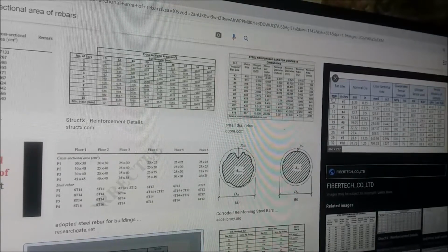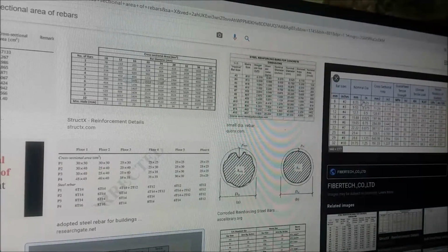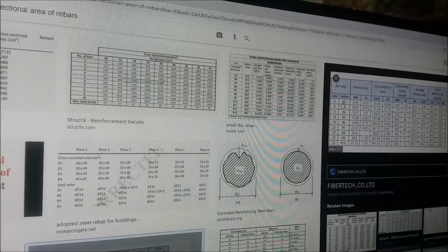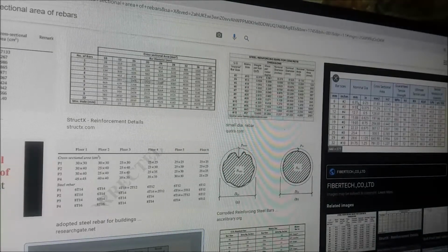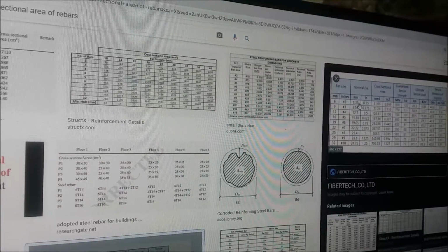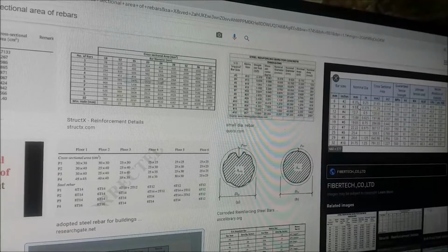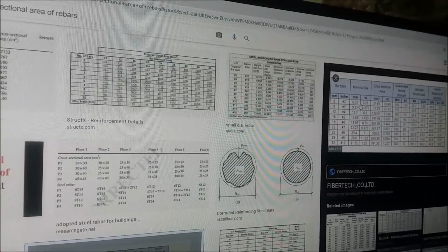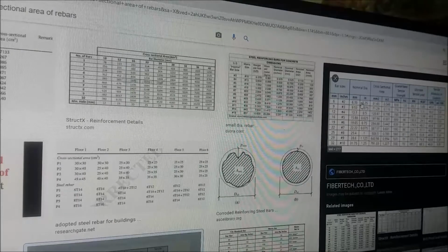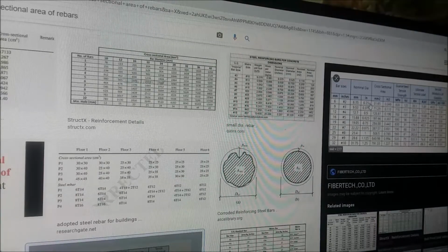Anyway, it's got the bar sizes in millimeters and inches. It's got the nominal diameter. That's what these bar sizes would be. However, that's not the cross-sectional area. Between the deformed parts it is smaller because some of the steel went into making the ribs. So you have to use the cross-sectional area of the parts that actually get to use. The ribs are what's keeping it from sliding through the concrete, but that's not determining how much area you're working with for the stress.